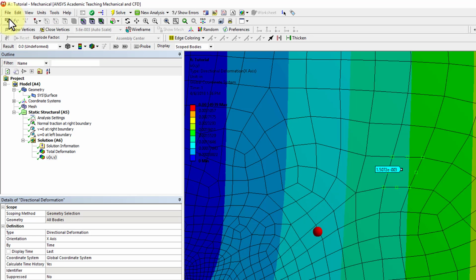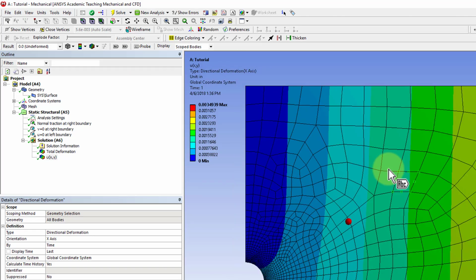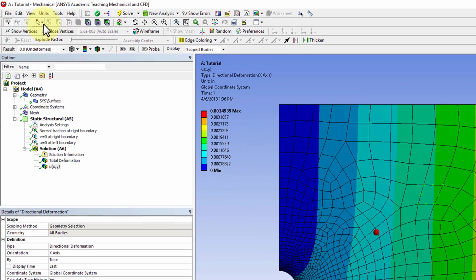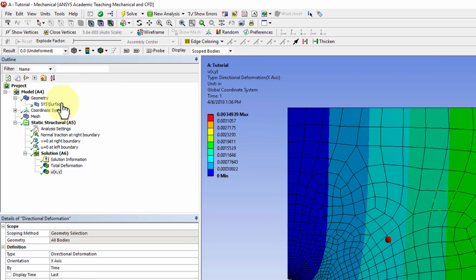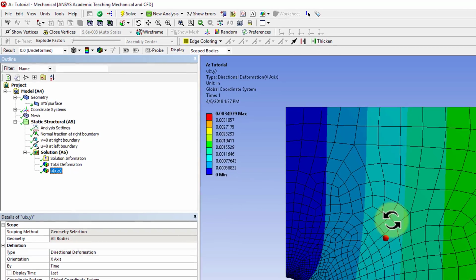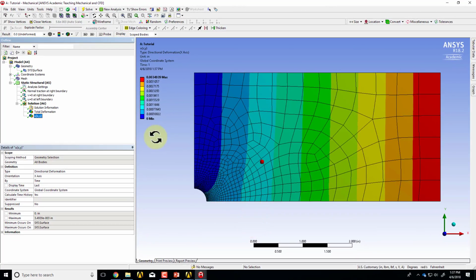Then I can delete that label. If I select this, I can click and select delete. Okay, it's not too obvious. I can zoom out here, and I think I need to say single select, or maybe go to geometry and come back to this view. Those nodes are not selected anymore, and that's all there is to post-processing the deformation.